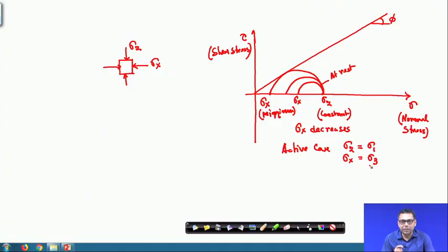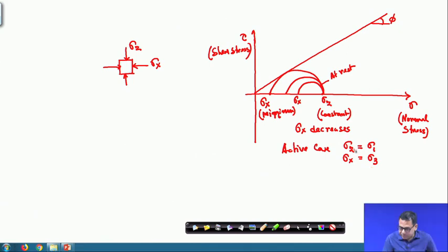If you represent them in terms of effective stress, then it will be with a bar or dash. Sigma z is sigma 1 because in this plane there is no shear stress, so all the stresses are principal stresses, sigma 1 and sigma 3.